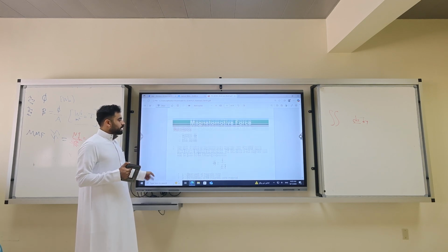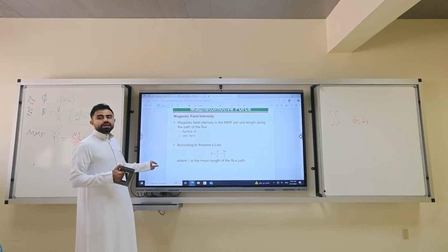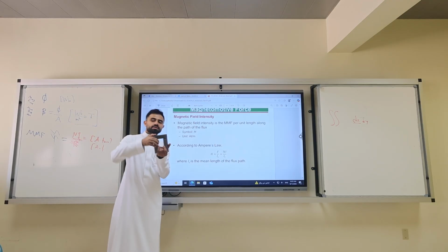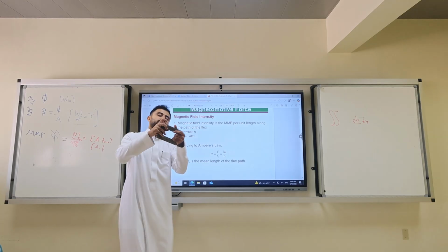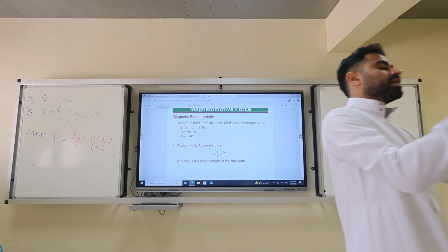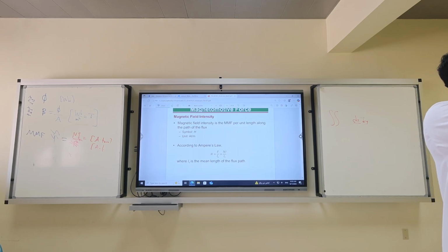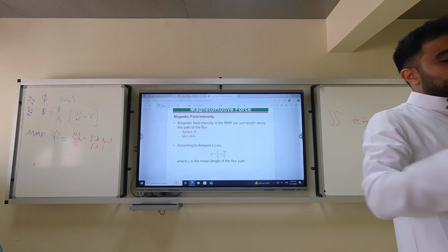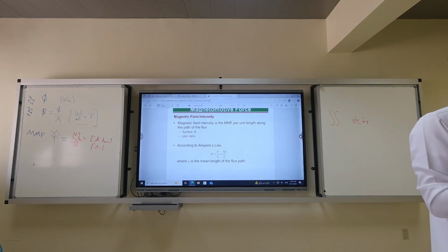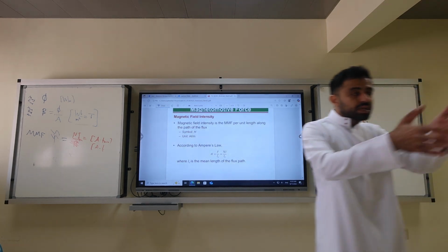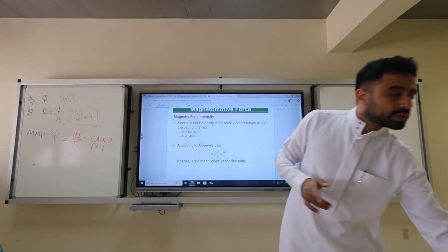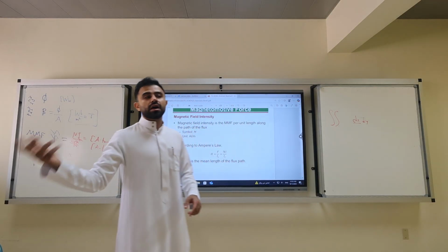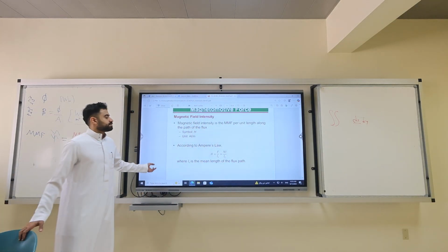That's what we will later call leakage. Sometimes in some designs you can see a little bit of air gap. Air gap means a distance. Maybe it's not purely rectangular, maybe there is an angle, so there would be leakage of the magnetic field at the corners. Maybe if there is a big magnet, a big machine here, it will get some of the magnetic flux. But in general, the steel would route the magnetic flux to go through it, just as copper guides the electrons to flow through it.